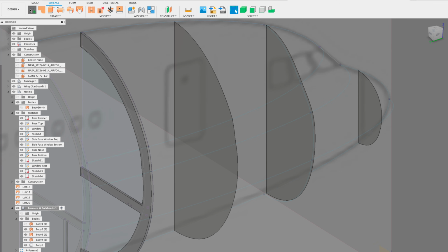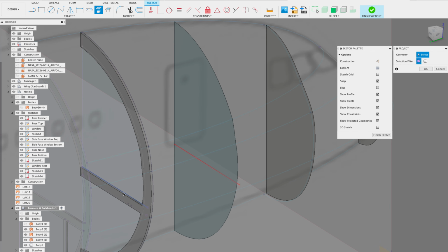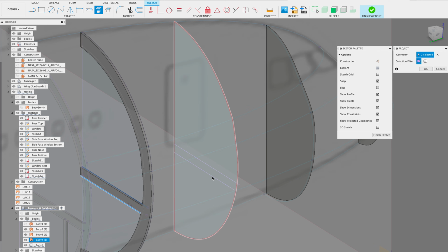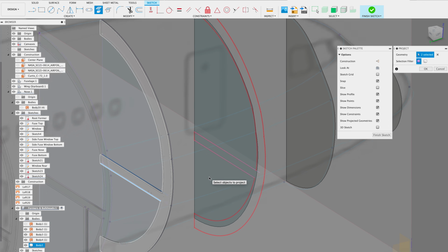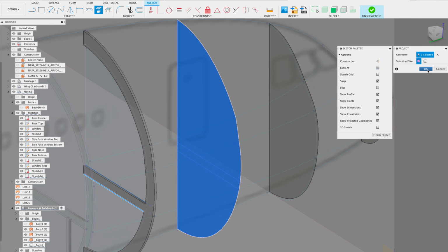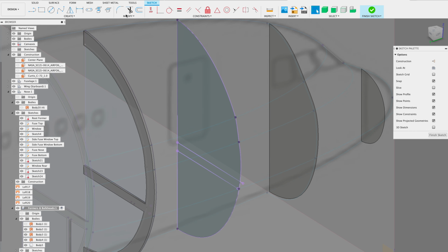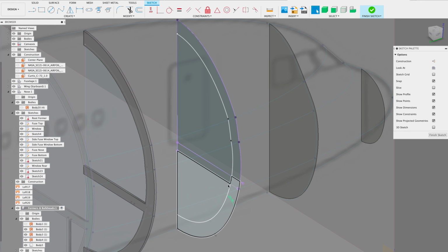I'm going to create a new sketch from here, and I want to project that line and the bottom line, and this time you can see it's cleaner because we don't have this little piece here that we didn't include. And then I want to use the outside like so, press OK. And the next thing is we're going to use the offset tool to offset the outer portion, like so. I'll pull this in 20 millimeters, press OK.